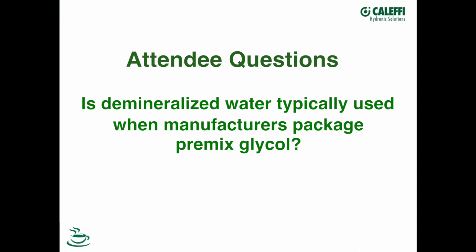Yes. Yes, and when you buy premixed glycol, you're getting a good base water. So it is important, especially with propylene glycol, to have a low ion content of the water. So whether the manufacturer does it and sells it to you as a premixed solution, or you take care of it in the field, in either case, getting, I think the term we've been using is zero-base water, getting that water down to a very low TDS level for use with glycol. Every application should have it.